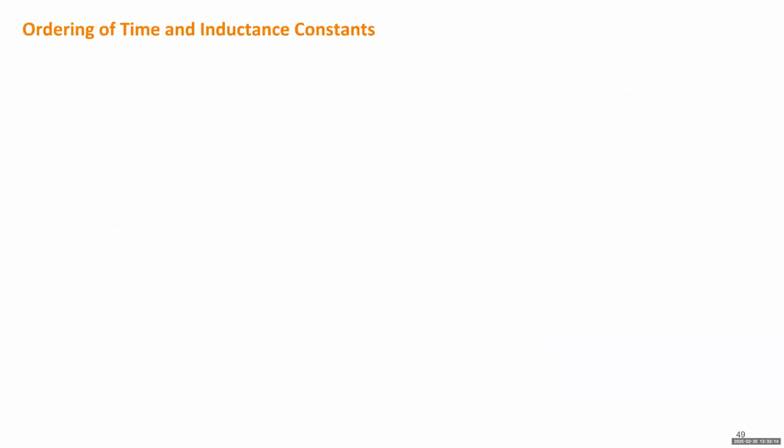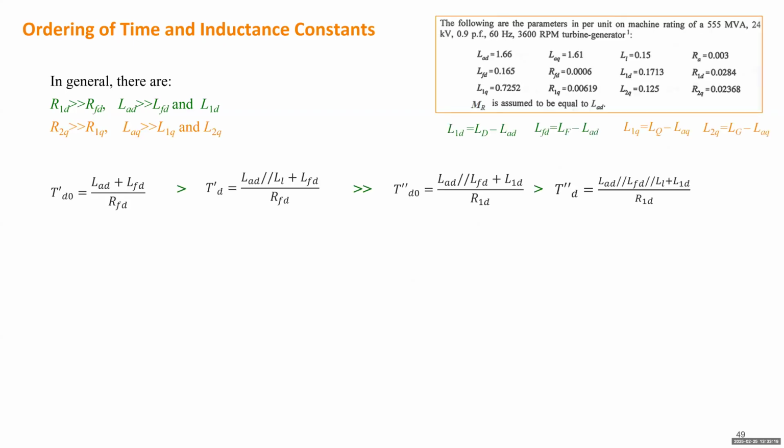This is the slide we just worked on. I already explained why this order has to be true: compared to that inductance, this one adds another parallel branch here. That has to make the parallel inductance smaller. So this one must be smaller than that one, and everything else is the same. So without the zero time constant will be smaller than with the zero time constant.